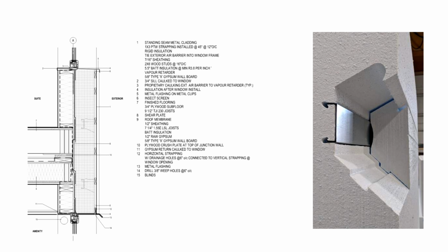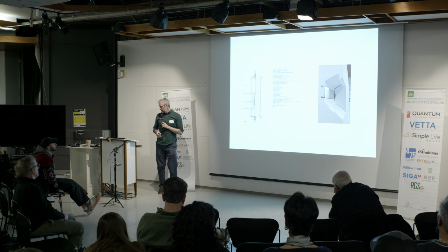It's basically a thermal-bridge-free product, because the track fixes the insulation through the sheathing, and then ultimately you're fixing your cladding through the insulation. You've got this central track, which you can see on the left, that just slots in. This portion is screwed into the wall, and then the strapping is screwed into that track. So there's really no connection from inside to outside but for the screw.